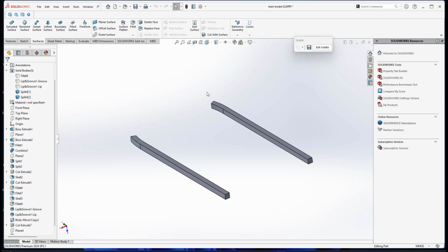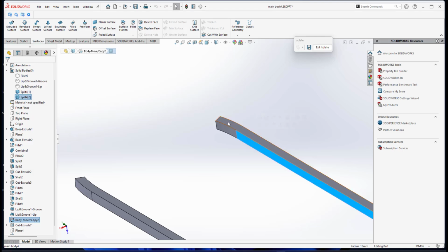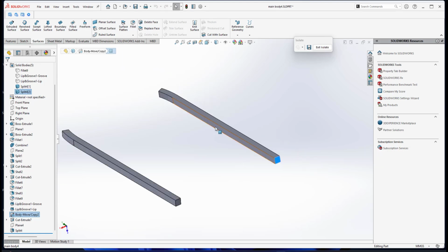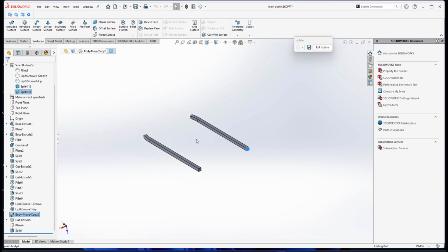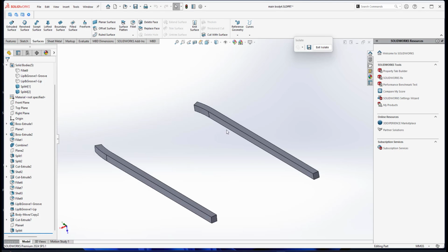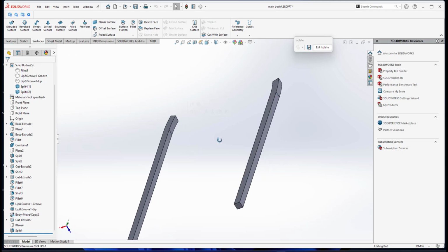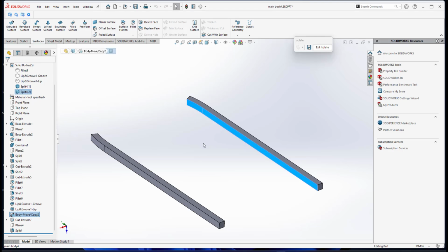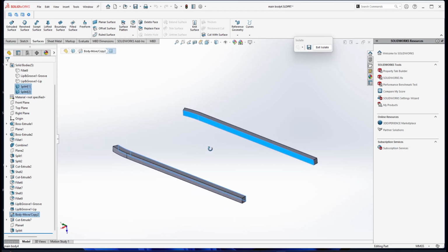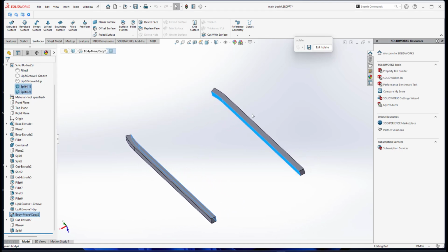when I go to surface mode, whatever surface, this is a single surface, this is a top surface, even here is also a surface, whatever surface, and you delete it, your object is no longer a solid body. It becomes hollow. It becomes a joined surface. It's not a solid body. For me to create half thickness of the ribbon, what I will do, I will select this surface, hold on, I do it again, I will select this surface, hold my control key, select this surface and this surface. Alright, this surface I don't want to delete it. The other surfaces I want to delete.